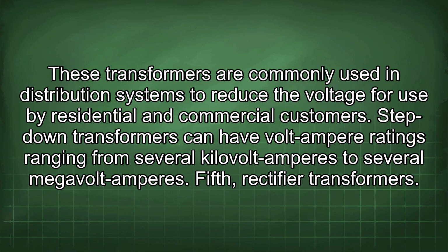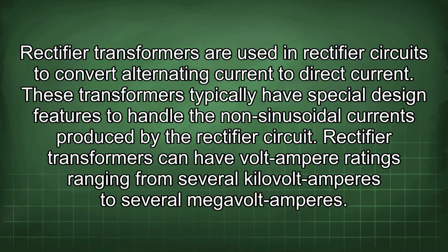Fifth, rectifier transformers. Rectifier transformers are used in rectifier circuits to convert alternating current to direct current. These transformers typically have special design features to handle the non-sinusoidal currents produced by the rectifier circuit. Rectifier transformers can have volt-ampere ratings ranging from several kilovolt-amperes to several megavolt-amperes.